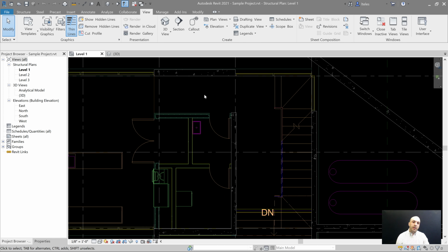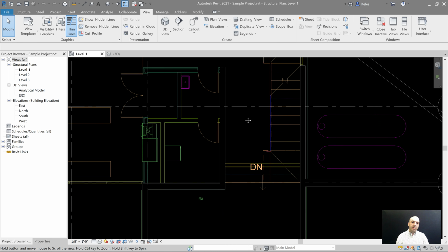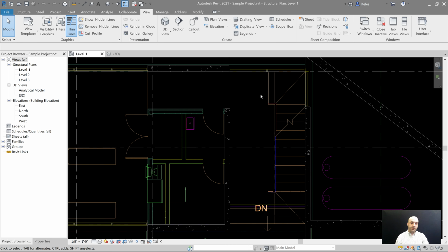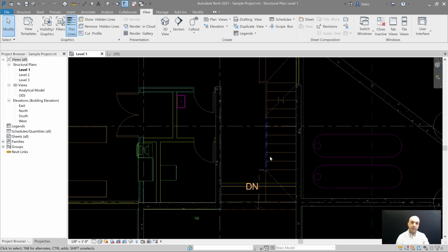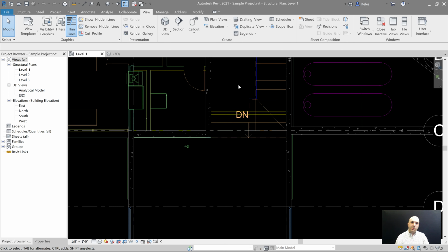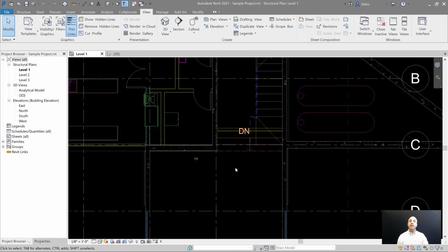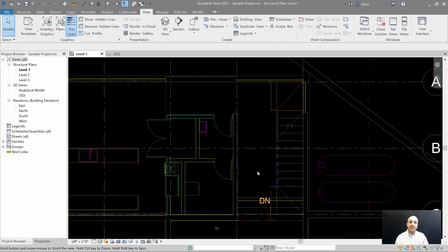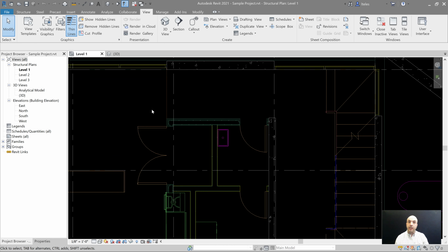And as we keep walking, we turn the corner, come down, there's some stairs that go up to the next floor. That's what these hidden lines represent, that these stairs continue up. But as we approach the family room, we see a down arrow and a couple of stairs. So that is a deliberate change in elevation. So right here, we have at least 2 floors that we need to model, 2 separate sketches. Use the change in elevations as your guide as to how many different floors you need to model at this level. But now let's go back to this line up here that we didn't know what it represented.